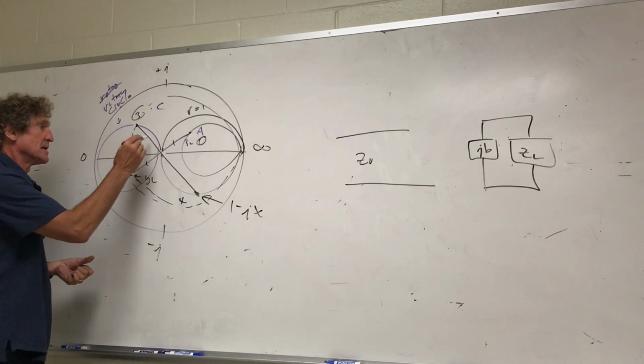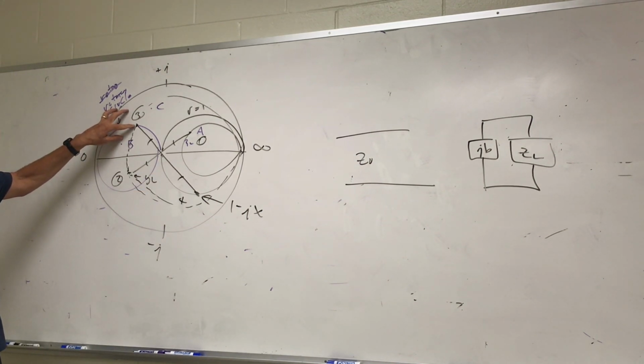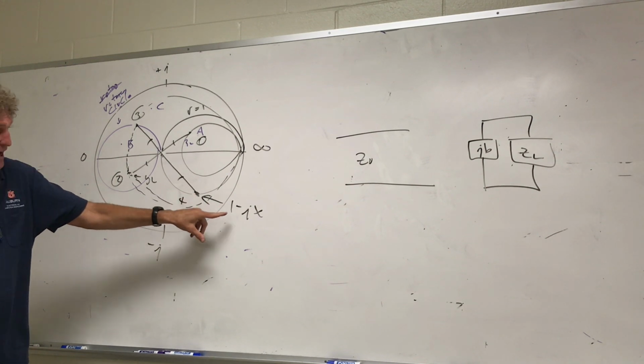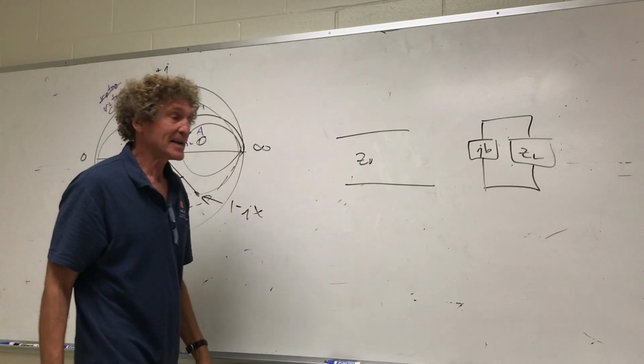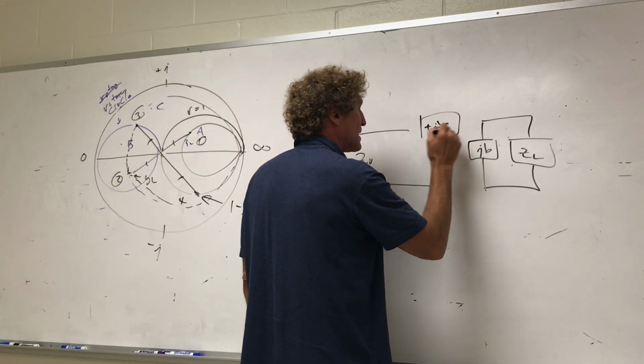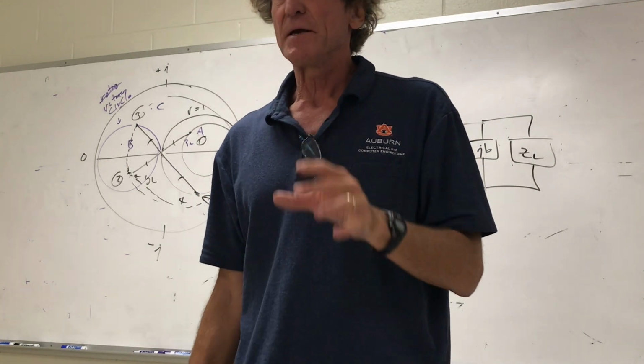And again, the only thing you're doing is finding the value right there of the admittance at this point and taking 1 over that to get here. And the real value you're going to get is approximately 1 every time, has to be. Now to get rid of that, the only thing I do is add a plus jx. And now that would cause it to be impedance matched.